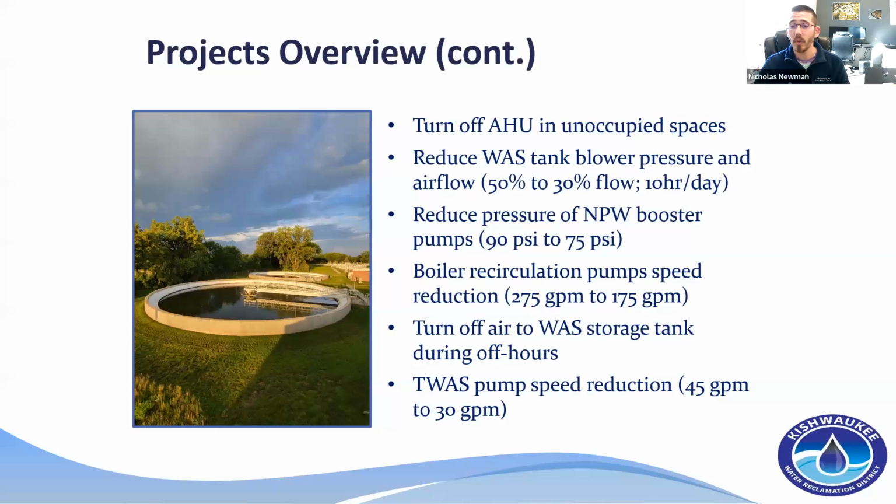Another one in our biosolids processing system: we use non-potable water booster pumps to help get water through the piping up to our dewatering and our centrifuges. And we were over pressure for what we really needed. So we dropped that from 90 to 75 PSI.